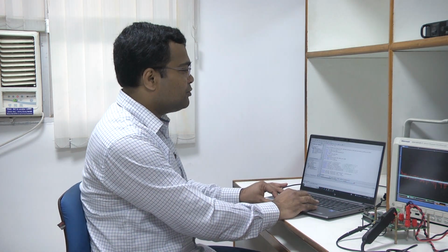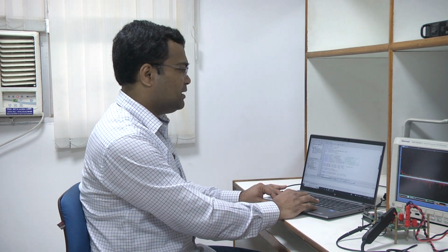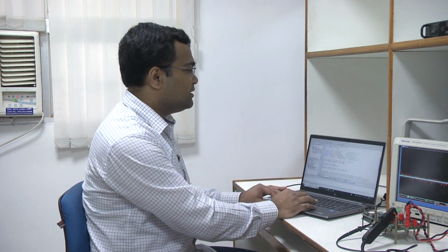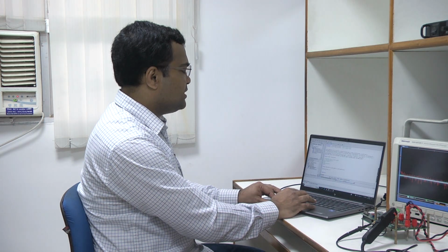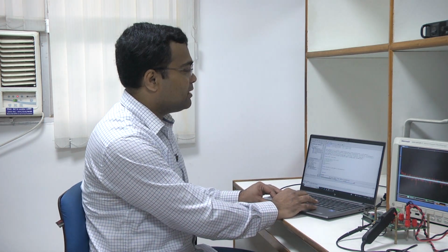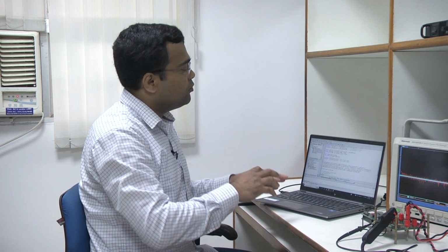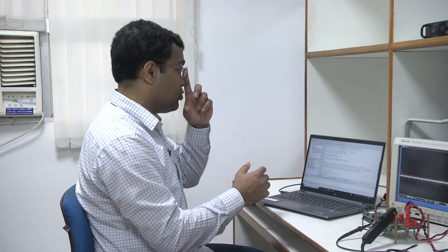Here we are using a fixed current reference, that means only the inner current loop is closed, and the outer loop is open. We are using two configurations demonstrated in the lecture: one is constant on time, where we are using a valley current of 2 ampere, and the other is constant off time, where we are using a peak current of 3.4 ampere. This code is made so that by changing the switch position we can move from constant on time to off time, so we do not need to run the code once again.